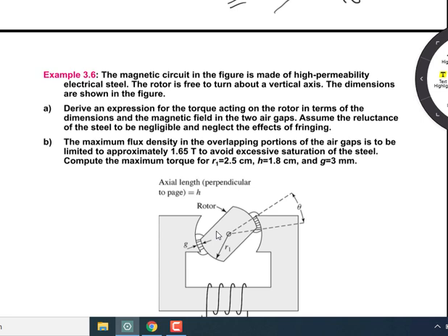So with an expression for the inductance of this magnetic circuit, here we can express it as a function of the rotor angle. Had we considered a rotor that is purely cylindrical in nature, then the system inductance would become independent of rotor angle. However, here as the rotor is salient, not cylindrical, the rotor angle makes a huge contribution in that magnetic circuit. It can alter it in a significant way.